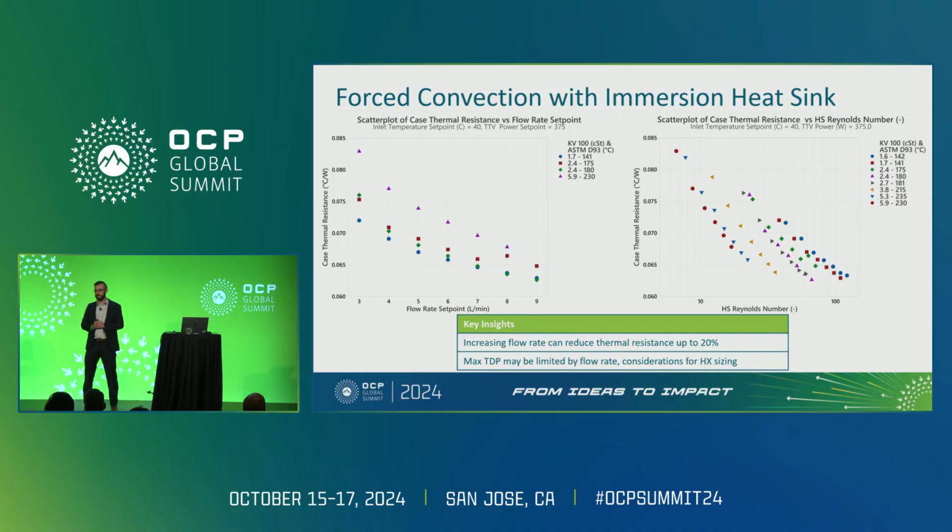The figures of merit that were put forth, I think, a year or two ago now, were derived from heat transfer correlations that were appropriate for perhaps a different application. They may be applicable, but certainly they were derived for natural convection, so when it's moved to forced convection, we probably need to reconsider them. In either case, we can either validate those correlations as we collect more and more data, or we can develop new correlations.